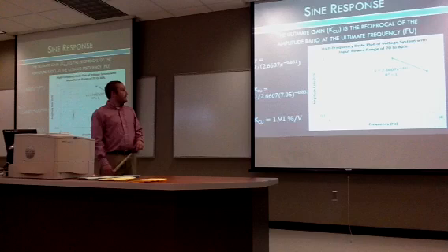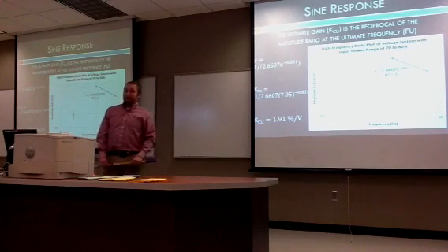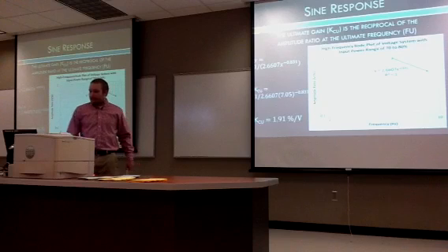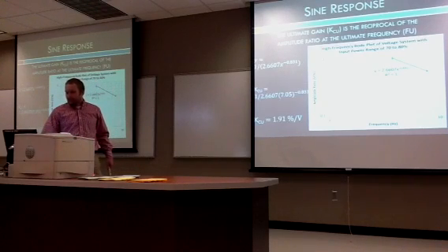KCU, or ultimate gain, is just the reciprocal of the amplitude ratio at that ultimate frequency. I did the same thing. I took that 7.05 hertz and I solved it; I used a power trend line and was able to solve for the ultimate